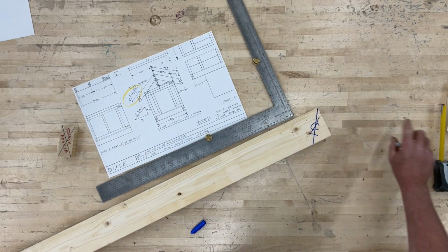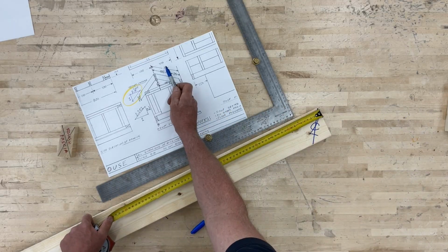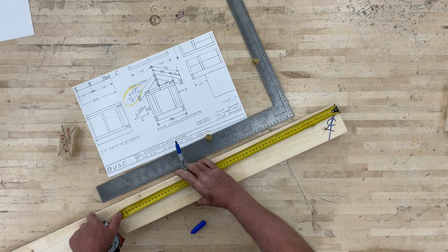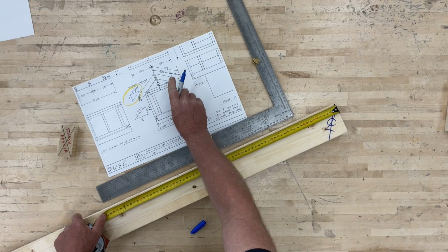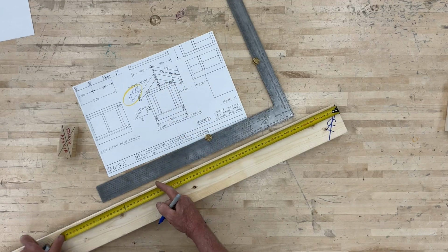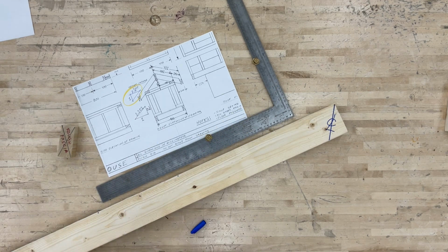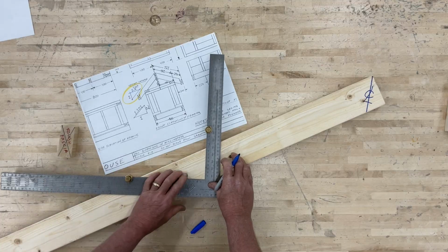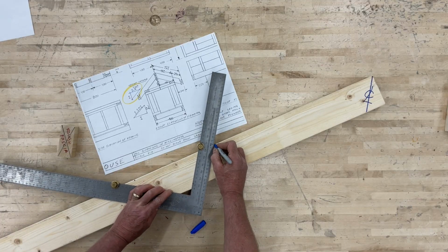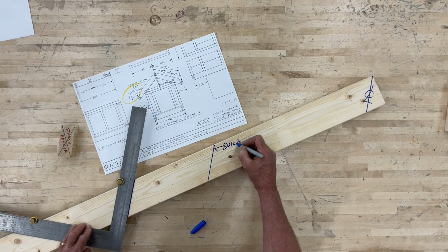Align your center line with the corner of the board so that a tape hooked on the end of the board will give a precise measurement. Measure along the top edge of the lumber and mark your measurements for the building line and the plumb line of the projection. Carefully mark these plumb lines with your framing square. It helps to label them as you go.